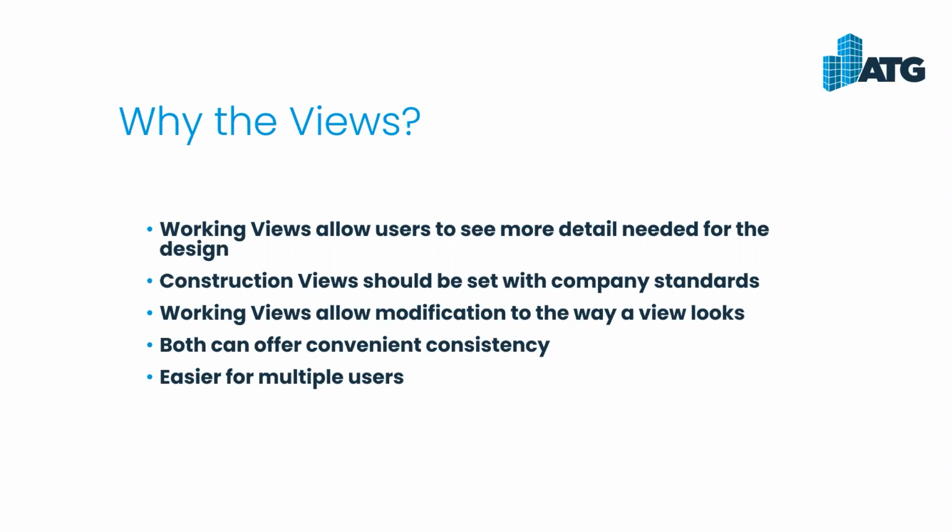You can simply go in and apply a view template. You can also apply a temporary view template if you haven't seen that. Down at the very bottom, right below your design area, you have an option where you can disable a view template temporarily and then bring it back after you've changed a few things. So it's a nice feature. I want to say that was added maybe 3-4 years ago within Revit. So I use it often within projects.